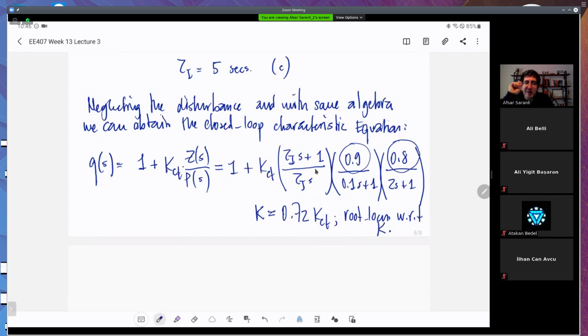Okay, so we will be plotting the root locus with respect to k, but there is a constant of proportionality between k and KCT. This becomes important at the critical points, like the j omega axis crossing or the breakaway points and so on. If you want to find those, you need to first find the k value, and then convert to KCT for your design. Okay,